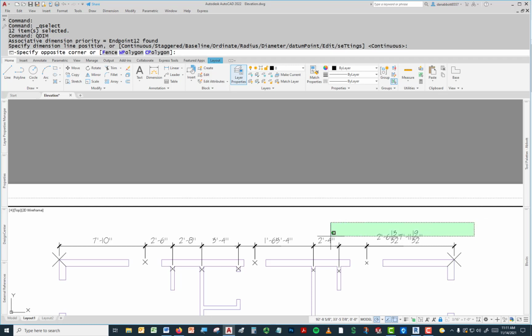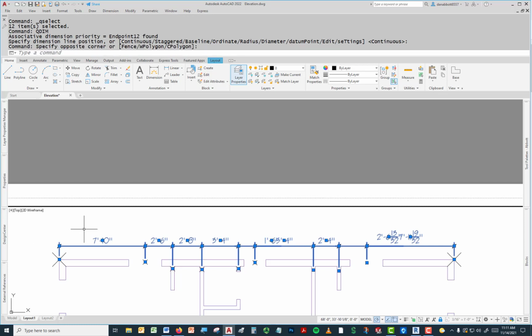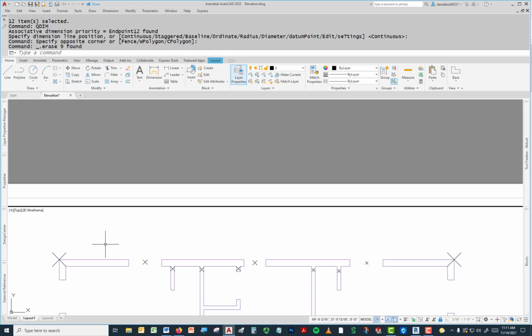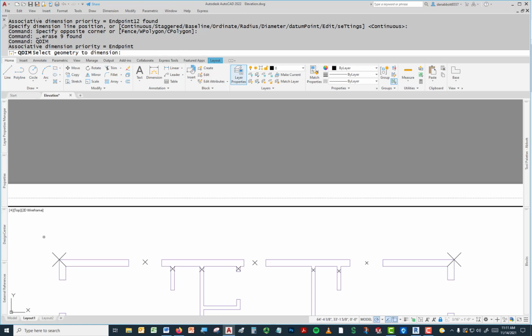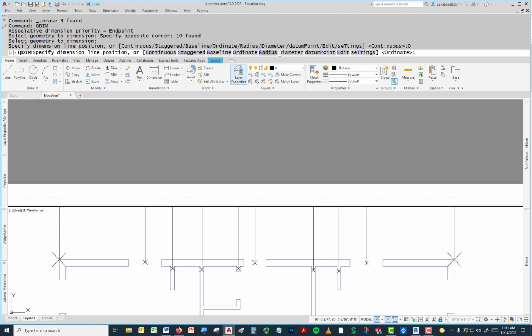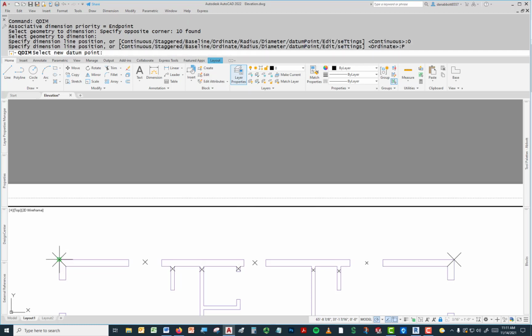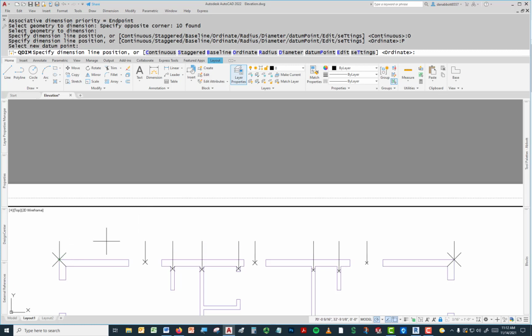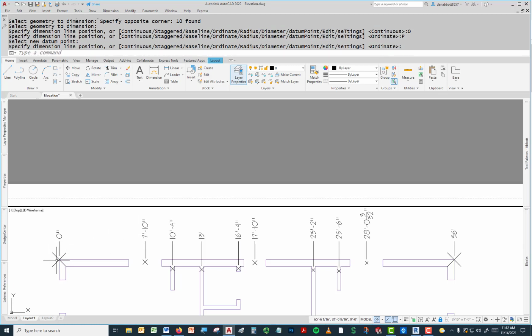I will say this, architects, my architect friends, I know that you always do your dimensioning that way, but as a machinist and somebody that has done a bunch of building and finds it much easier to lay out the location of all the interior features and the exterior openings, I personally think that it makes a lot more sense, instead of doing continuous, to do baseline, ordinate. In other words, that, which means I've got to pick a datum point. Say my datum point's going to be right here. Now I put my dimensions in, and every dimension is a location from the base point.